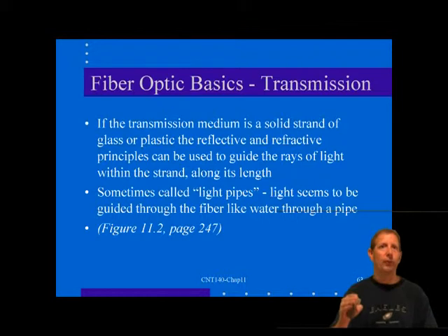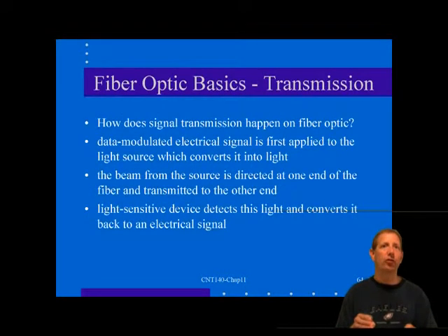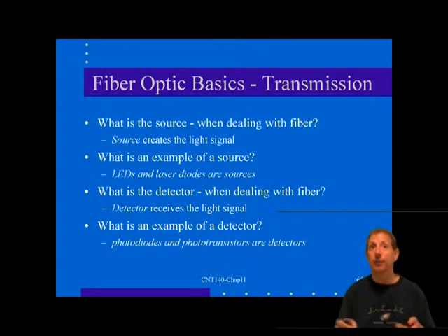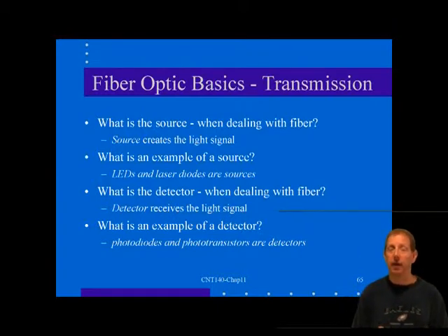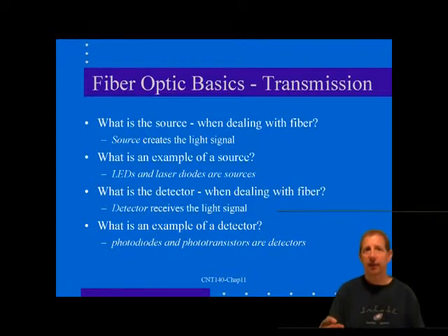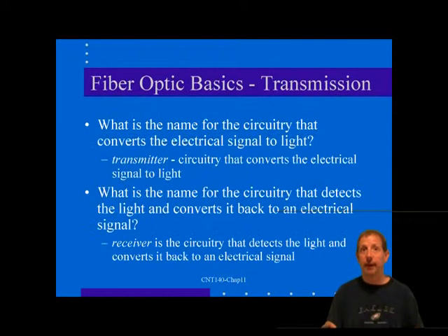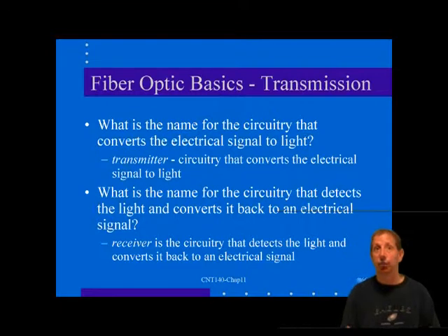A precision tool, which is basically like a wire stripper, is used to exactly cut the buffer sleeve without nicking the bare fiber. The plastic buffer is then removed by gently pulling a stripping tool toward the cut end of the fiber. The plastic primary coating may also be removed during this process. The fiber is then cleaned with an appropriate solvent, such as alcohol. After some additional steps, the remaining bare fiber is then trimmed, terminated into an appropriate fiber connector.